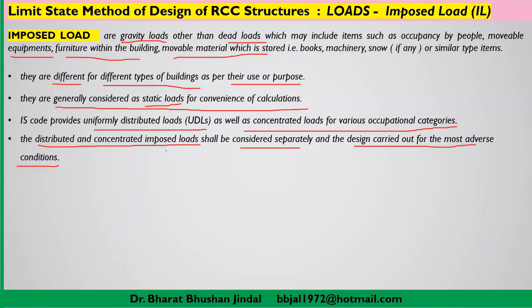So you will come across the term combination of load later on. That means when you are going to design a structure, you have to follow that combination of load which is going to offer the most adverse condition, so that our structure is designed for the adverse possible conditions which may happen during its lifetime.